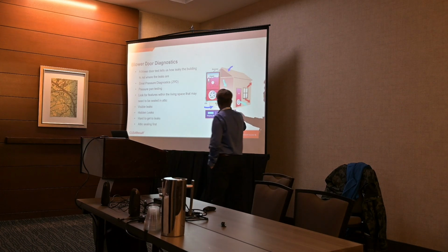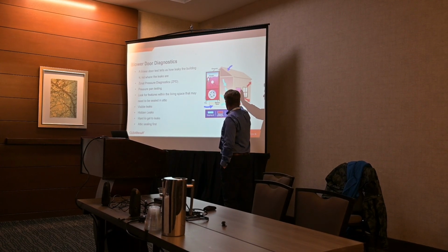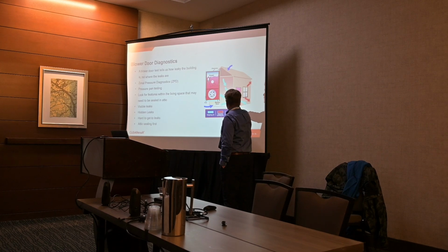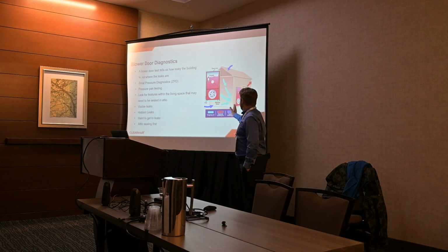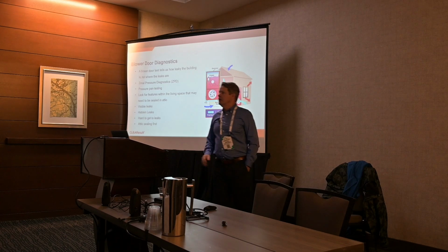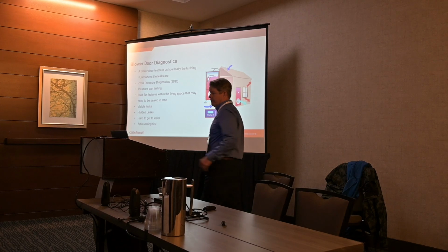I went out to a lot of new houses when I was a home energy rater, and we do a blower door test on it, and the insulation is here in the frame floor, and we do a pressure diagnostic to the basement, and it comes back at like 4 or 5. And what that tells us is the pressure boundary is here, and the insulation is there. So what does that mean? It means it's not working, right? In a brand new house that people just bought.